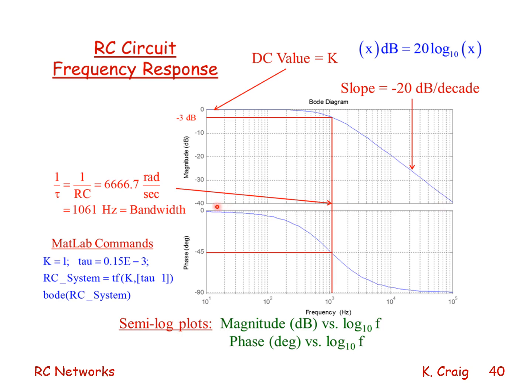And in the magnitude scale, the vertical axis, the magnitude, the amplitude ratio, output over input, is determined by dB, decibel, where the value in dB is obtained by multiplying 20 by the log to the base 10 of the number that we want to convert to dB.